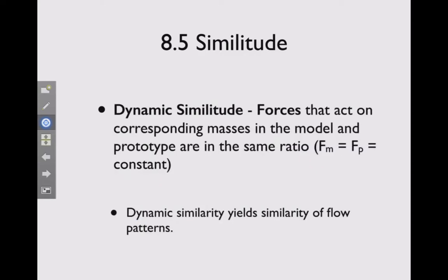The dynamic similitude is a little bit more complicated, but it allows some very powerful techniques that we can use in prototype testing, model and prototype testing. So this is very key to understand that dynamic similitude is not dealing with geometric dimensions, it's dealing with forces. It's saying that the forces that act on a corresponding mass in the model and prototype are in the same